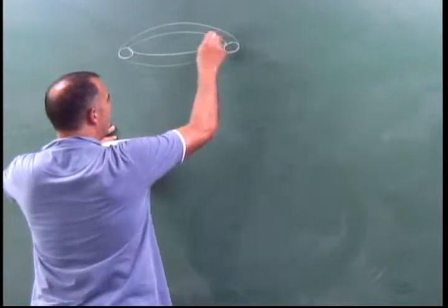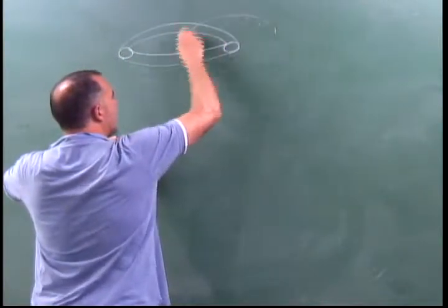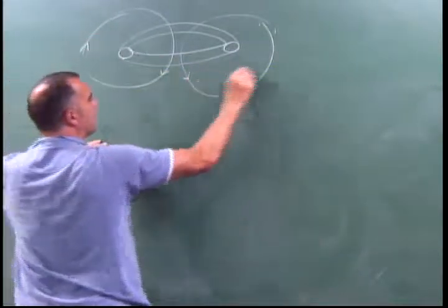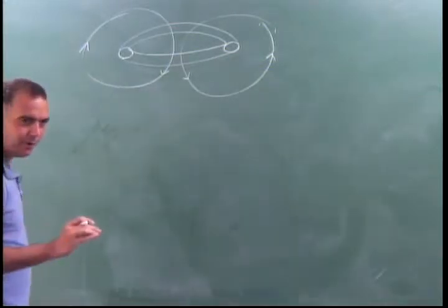The reason these are stable is that they're embedded within a vortex. If you remember Rayleigh plateau, imagine this is now embedded within a vortex, so you have a flow like this. As the thing tries pinching off, it'll actually be stabilized by the rotation, because rotation wants to throw heavy fluid outwards. So it doesn't want the heavy fluid coming in, which is what's needed for a Rayleigh plateau.